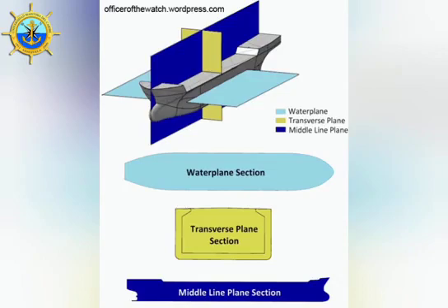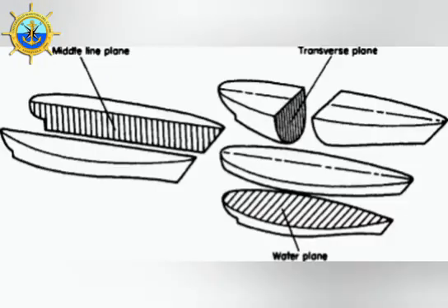In this video, he tells us a little about the parts, dimensions, and structure of the ship, in which we have the hull, which is the mold or exterior covering of the ship. It is what surrounds and waterproofs the structure of the ship, thus forming the body of the ship. Depth is the height of the ship, or vertical distance in meters measured from the lower face of the hull at its intersection with the keel to the main deck line, measured in the middle of the length.